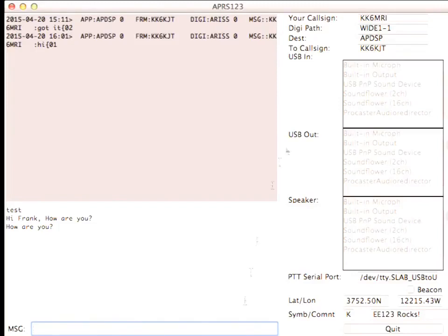And this is, if that is transmitted over the APRS, it will actually be digipeated. So you can do that from your house, and it will be digipeated. So be careful, until you debugged it, don't go to the APRS frequency because you might mess up other people's systems. Okay? So just be careful. Don't overload it. Don't transmit like for an hour on the APRS frequency and block the entire Bay Area. So this is a nice application that you'll be able to use.